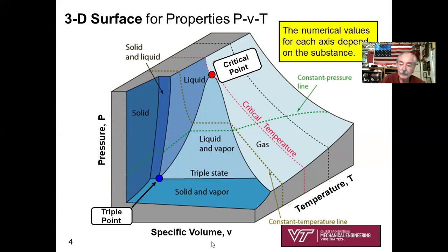Let's look at the basics. It's three dimensions, kind of like X, Y, Z. One axis is pressure, P. That's the vertical axis. The horizontal axis is specific volume, little v. And kind of like the Z axis is temperature. What I want to remind you, and sometimes it's hard even for me to visualize, is that there'd be a bunch of dots that lie on these swoopy surfaces. Some are steep, some are not so steep. They're different colors of blue, but recognize that all these colors of blue represent a three-dimensional surface.